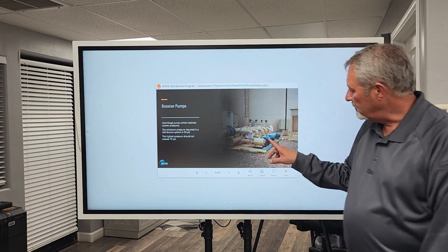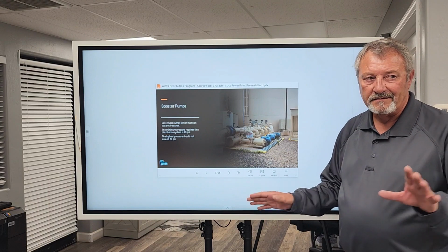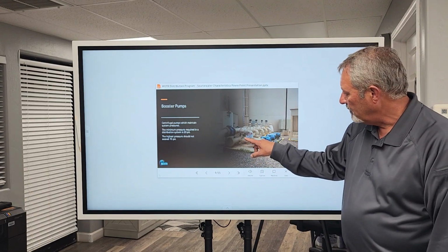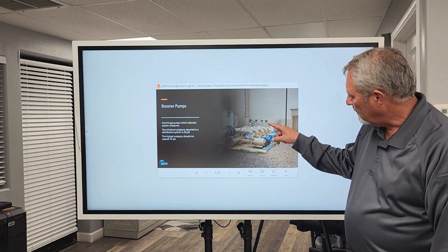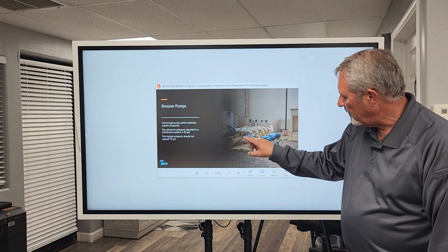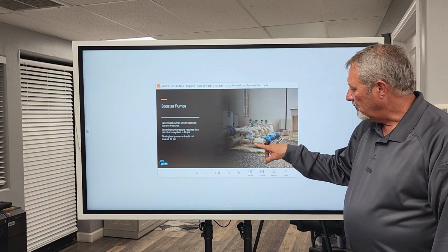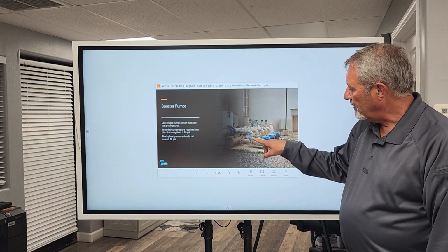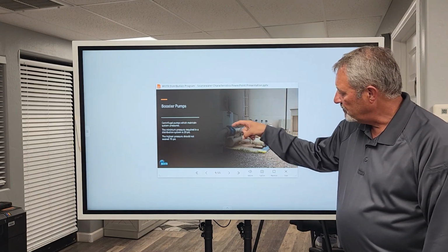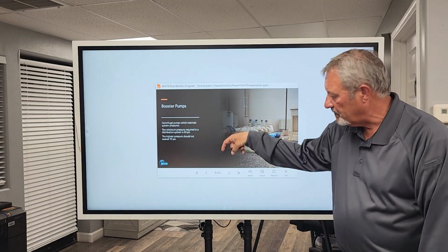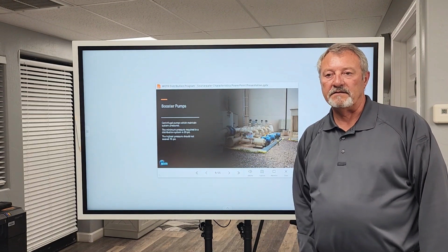And by the way, just so you can see here, and we're going to talk about this a lot in a different video, but the water is being fed through this pipe. It comes out of the ground storage tank, goes up to this pipe. It feeds those pumps, keeps them primed. When the pumps are pumping, they're kicking it up at a 90-degree angle into the distribution system. That's where the 90 is down here, goes underground into the distribution system out to the customer.